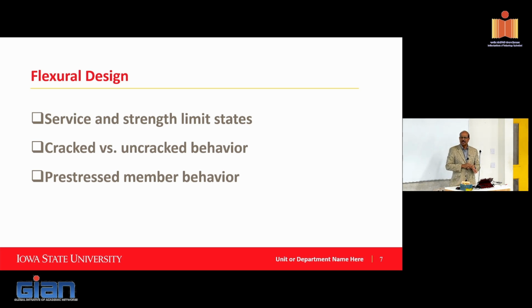It's not ideal to allow a pre-stressed member to experience flexural cracking like regular reinforced concrete. I think reinforced concrete can crack under service load conditions. Cracking will induce water ingression, and then corrosion. So in precast pre-stressed members, the pre-stressing plays a key role. It basically keeps pieces together. So if you cause corrosion to the pre-stressing strand, the consequence would be much more severe compared to reinforced concrete. So it's often designed to be crack-free.